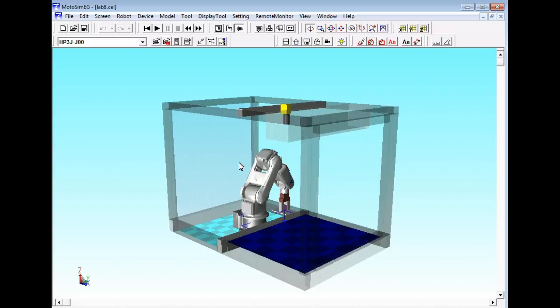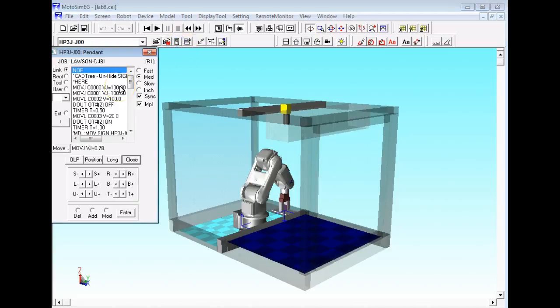I'll show you what. So notice this is the work cell for the Motoman robot, which is one right behind Josh. Of course, what you do in your 3D model is you can set what we call the opacity of the unit, so you can make stuff that's solid so you can see through it. Of course, you can't see through those metal bars up there. It just makes it easier to write your program. And what we do is we have a simulated T-Spin, and what we can do is we can jog the robot. You know, see it?